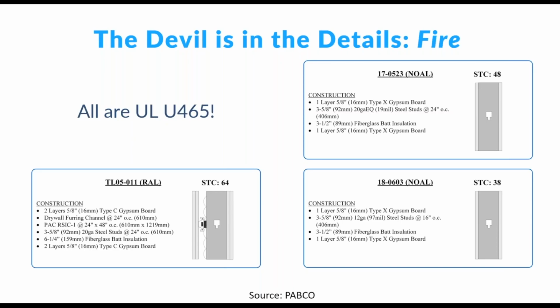But this uses a resilient sound isolation clip to isolate the drywall from the studs, and it's got more layers of gypsum board. It exceeds the requirements of U465 for fire, but it still fits within it. And acoustically, it provides much better performance than the other walls.